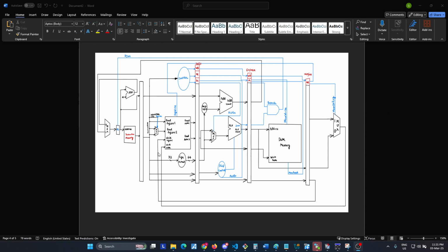As you see, we have a PC, an instruction memory, an adder that calculates PC plus 4, the pipe, the instruction memory that sends data across the pipe towards the ALU, the branch, the control unit, the data memory, and the memory write-back stage pipe along with the write-back to the register files. I'm not showing the HDU and the forwarding units here, but they have been incorporated into the code, as we'll see very shortly.